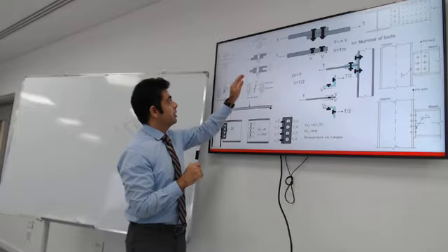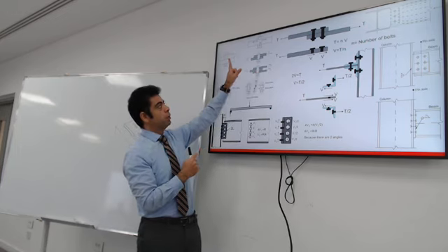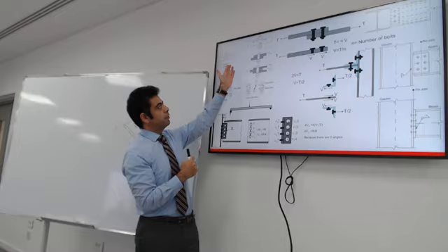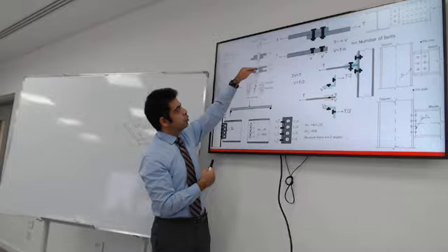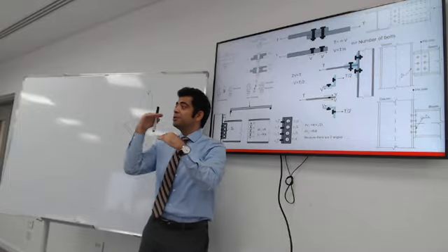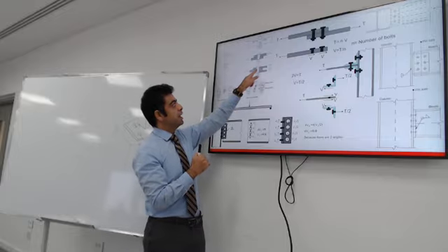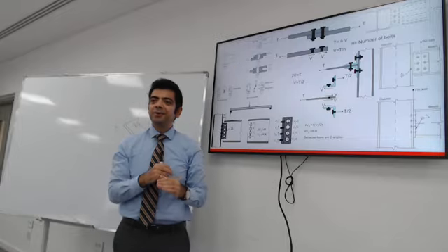If the connection is holding more than two pieces with one bolt, one direction will have two plates and the other direction will have one plate. When you pull them together, there are two shear planes. There are two shear surfaces. And then the force on each plane is half the tension going into the connection.